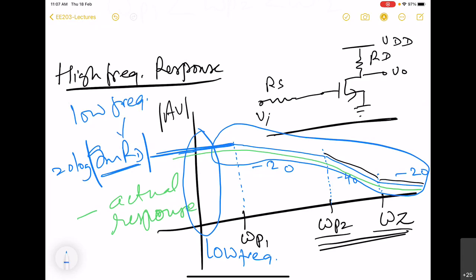We are familiar with this term, and this is actually the voltage gain for low frequency. This is what we arrived at when we started the discussion of the amplifier. But keep in mind, all these results that we have obtained are for this circuit, where we haven't included the biasing resistors. These R1 and R2 have been excluded, assuming that they are very large.